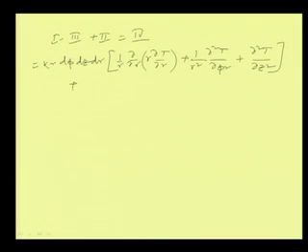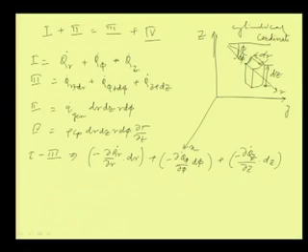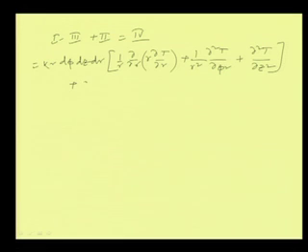Plus the second term, we have seen, is q dot generation into r d phi dz dr, and that will be equal to the 4th term, which is r d phi dz dr into rho Cp into del T by del t.